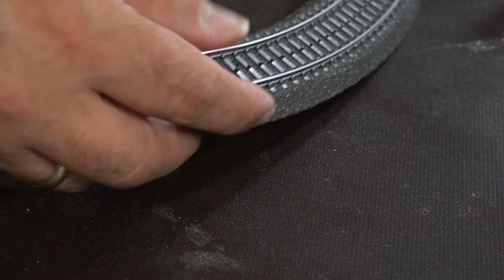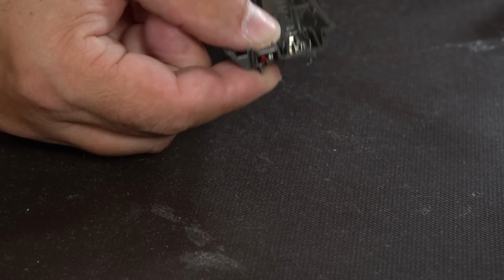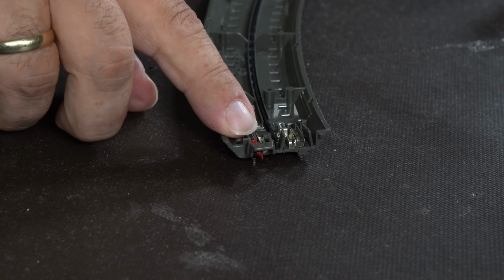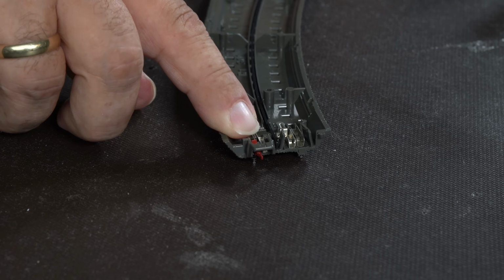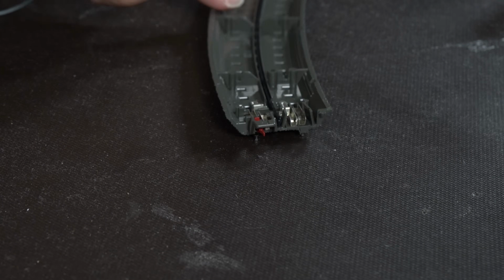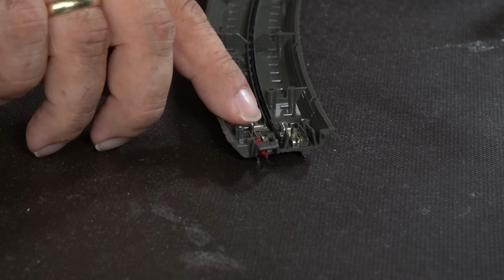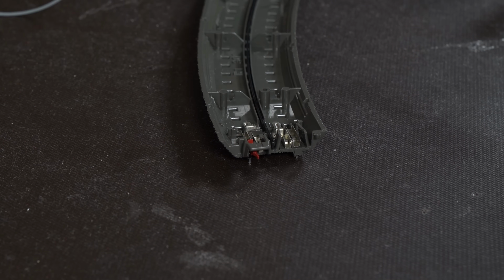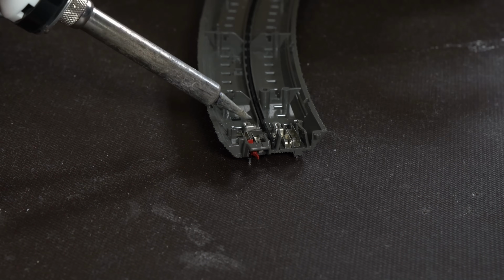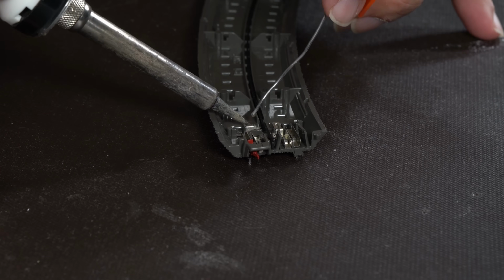So I turn the rail over, keep my finger on it if necessary, and then I know exactly where the tab is located. That is the insulating cap right at that spot on this side. That's exactly where the contact should be made. That means I can solder the cable directly onto this tab here if I want to. As a first step, I always warm it up a little, very gently, very carefully, and then pre-tin it.